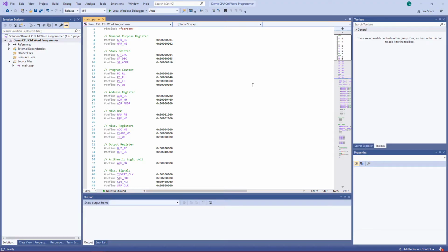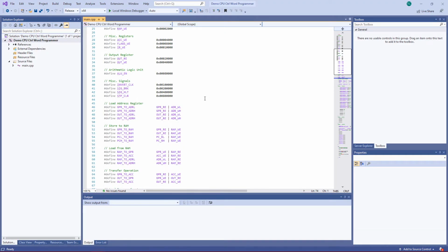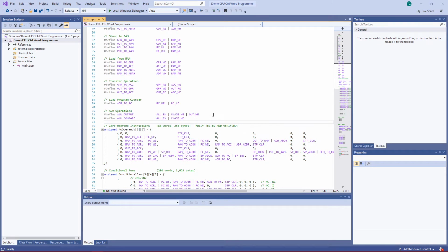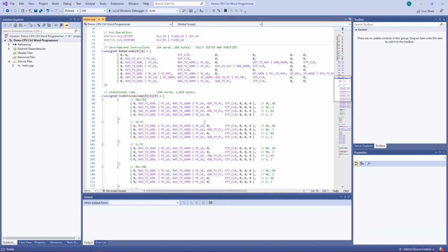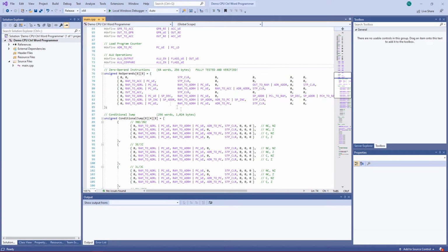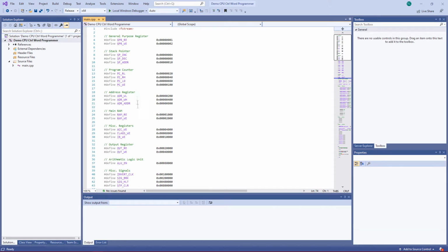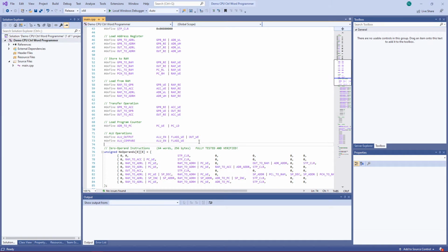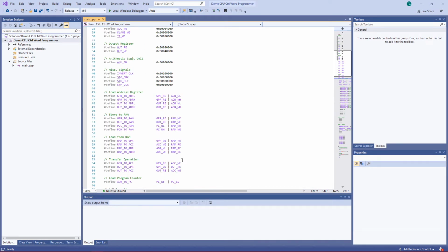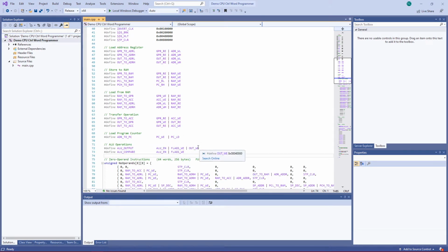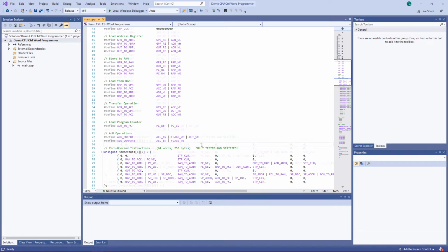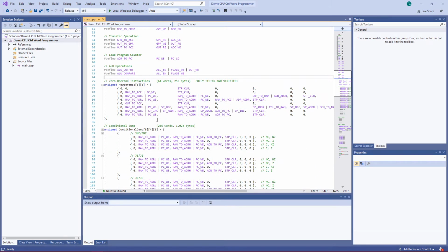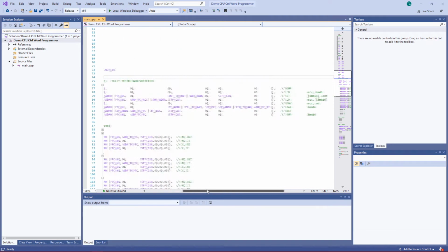Now here is the entire program so far for generating the ROM files. So what I've done is I've made a set of constants which represent control signals. I even made some that are a set of OR operations between 2 or more constants. Here's the entire data set for the first ROM. This one is complete, and you can kind of see what all I did.